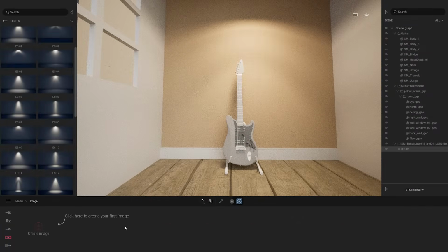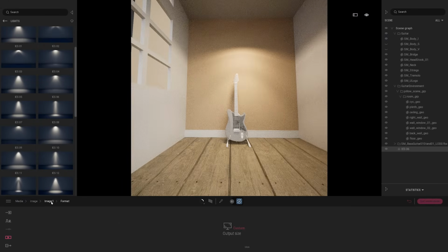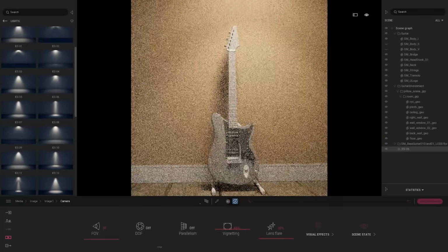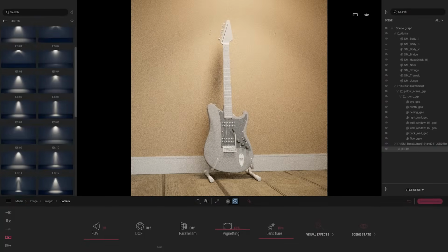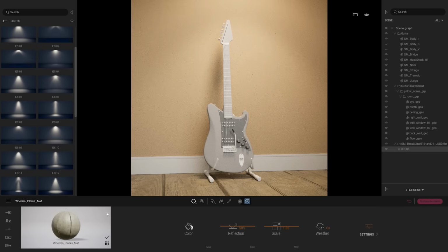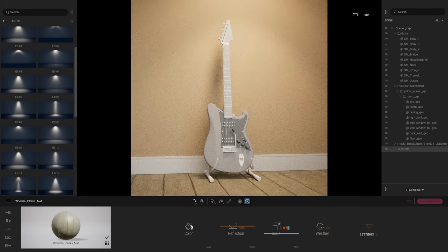Let's place down a camera. So clicking on plus, placing down a camera. Same thing here, I'm going to change the resolution because I want to have a square resolution, a square image. And I also want to be closer to my project with a focal of 30, that will be great. So that starts to look pretty good. So now, material picker, let's work on the material. I selected back the wood planks because they are too big, so I'm going to 0.5 will be great.